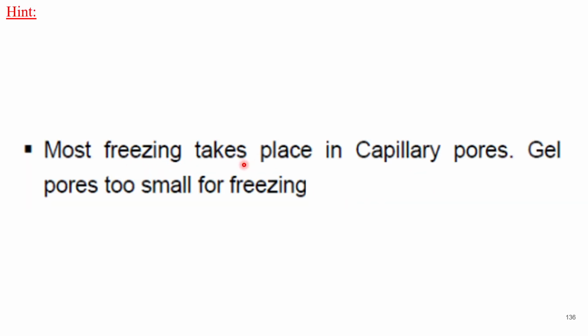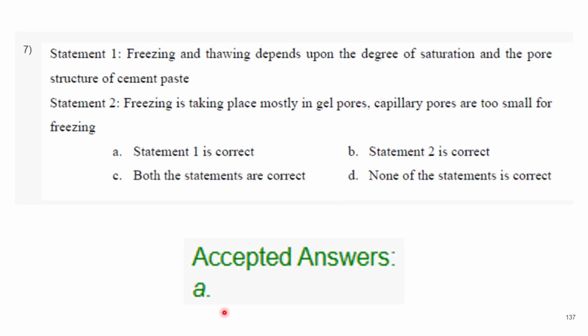So this is the correct one. A is the correct option. Most freezing takes place in capillary pores, and gel pores are too small for freezing. So the accepted answer is A.